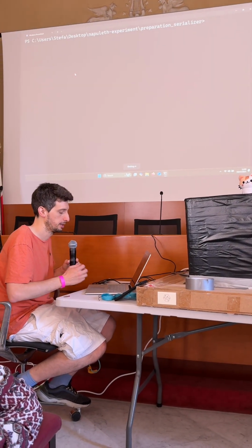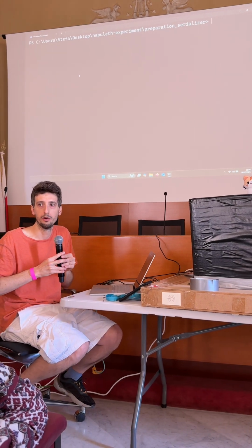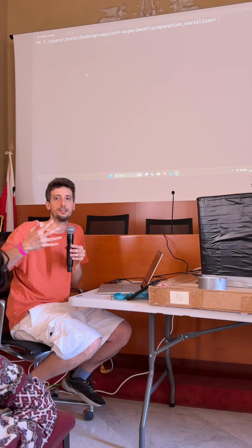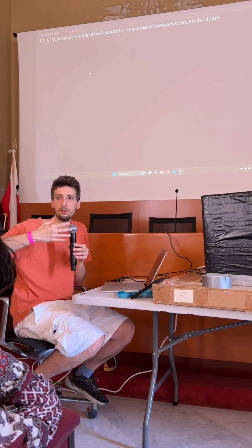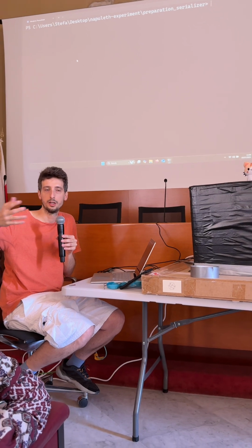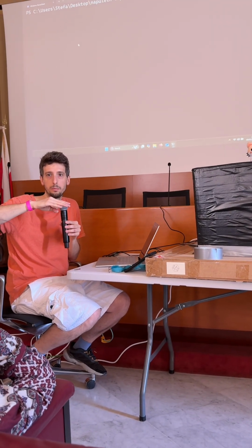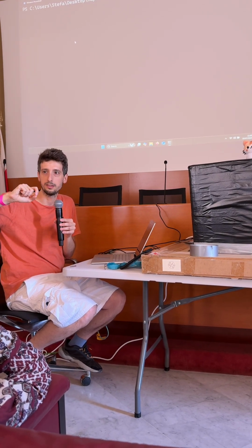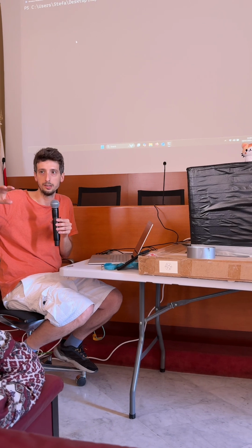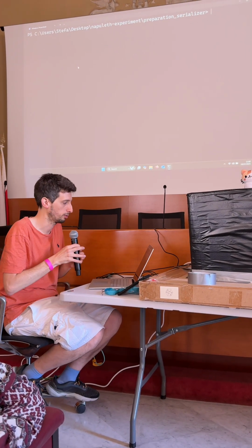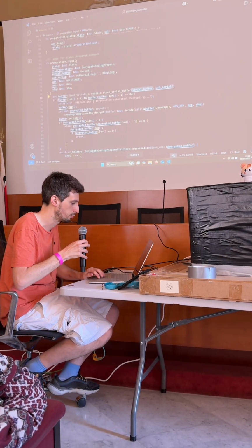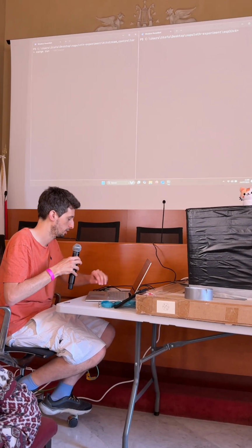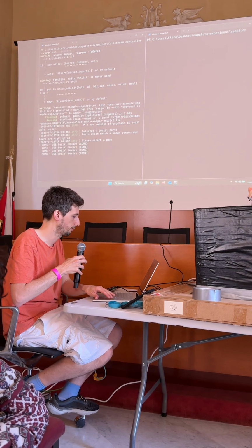So first things first, there is a bit of the protocol that involves the secret that these two enclaves should have. The information in this secret is a couple of tables of bits that need to be produced. There are 2 rows in this table, and we need to pick the ordering of the bits in the table, so whether 0 means X or 0 means Z. This is the secret information shared by the 2 TEEs. We put it as the first input of our program, so let me flash the 2 chips and run the programs. First things first, I'm going to flash. Program 1 goes on COM4.